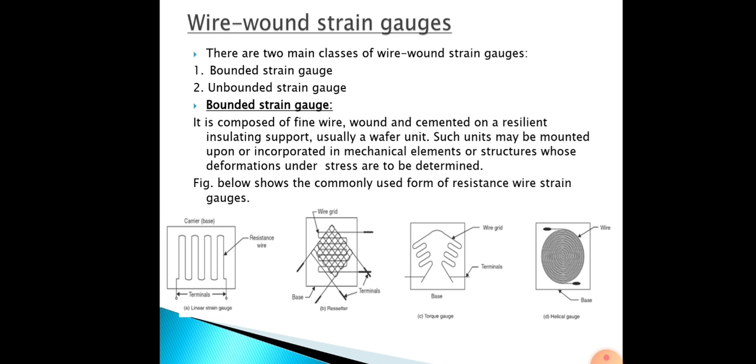You can see there, these wires will comprise the four arms of the Wheatstone bridge network, of which two opposite arms are tightened and the other two slackened by the displacement. So two arms will be tightened and two will be slackened, depending upon the movement.